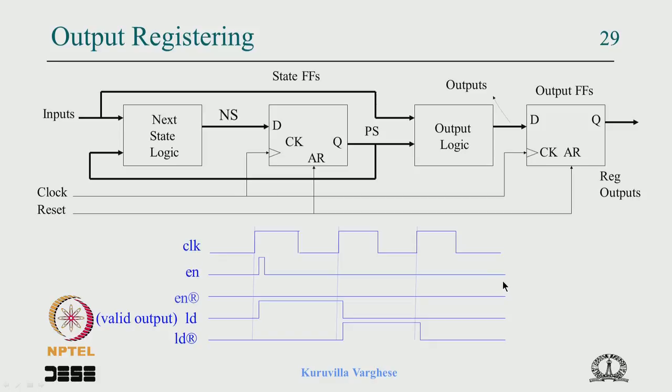the timing. You have to analyze the timing, what happens, because this output is going to the data path and the data path is giving some input, and this latency can reflect some time in the control algorithm. So you have to think, don't just put the output register and assume that everything works. Please analyze the timing. You can think of situations where this makes a difference to the control algorithm, something needs to be tweaked for proper work. You have to keep that in mind.